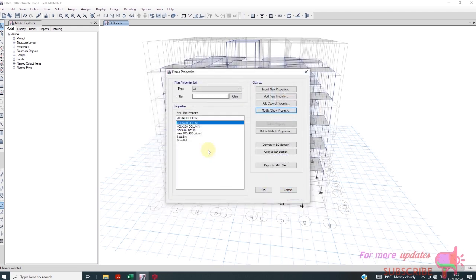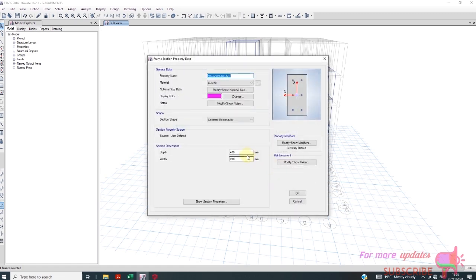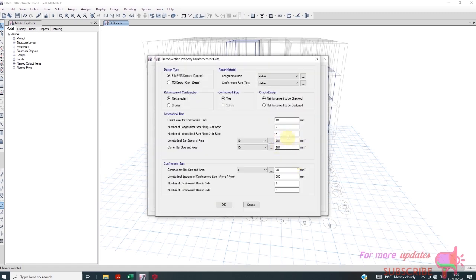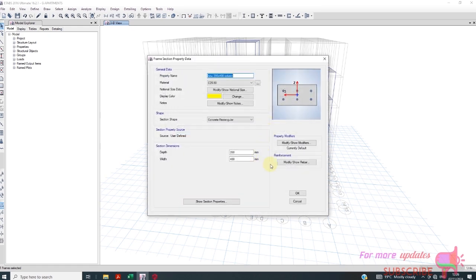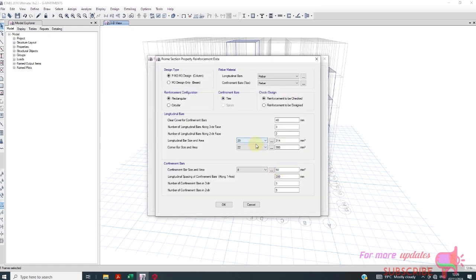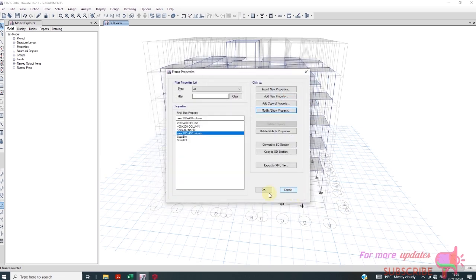So okay, we have that type of column. I have this type of column. It's just the orientation has changed, but it is more or less the same thing in terms of rebar size. And I have this another column here. Now this one, let me change this one to T20. So we need 4T20 corner bars, right? So then 2T20 intermediate. Okay.